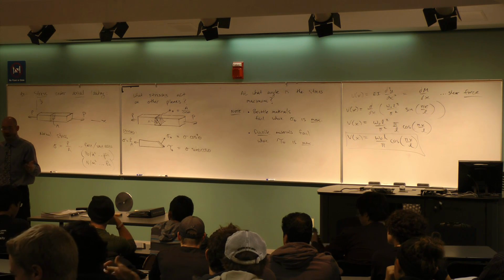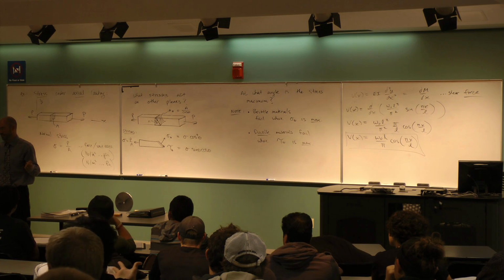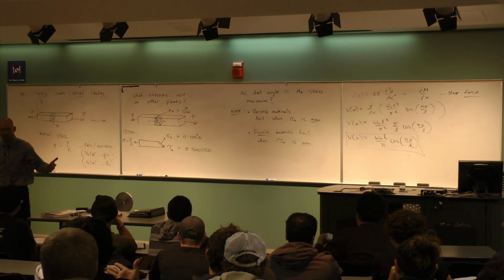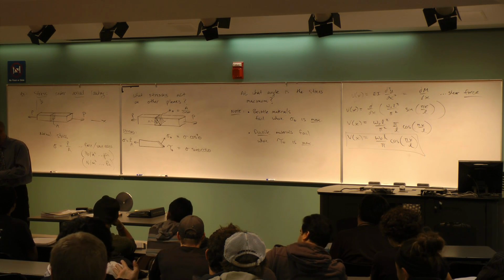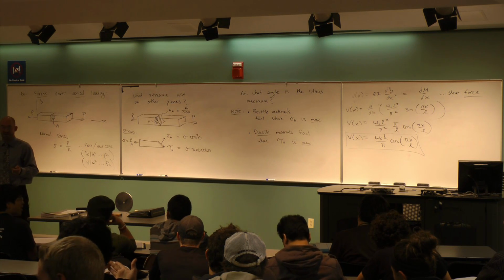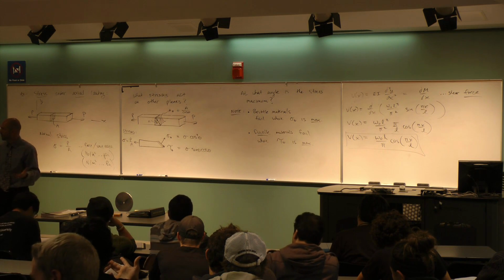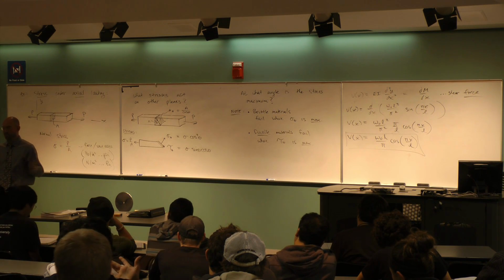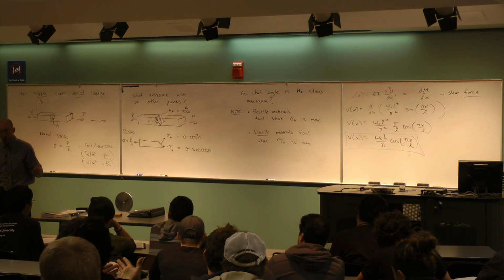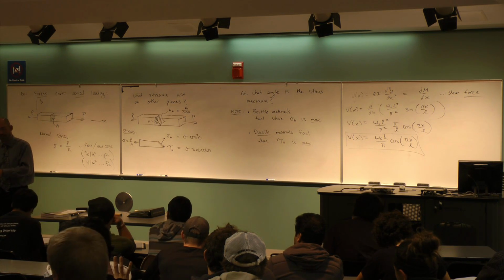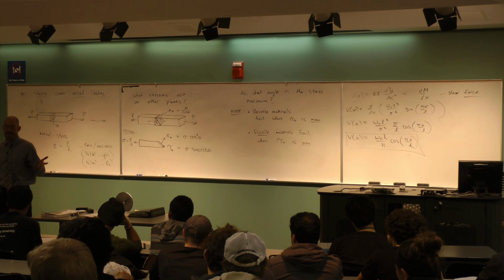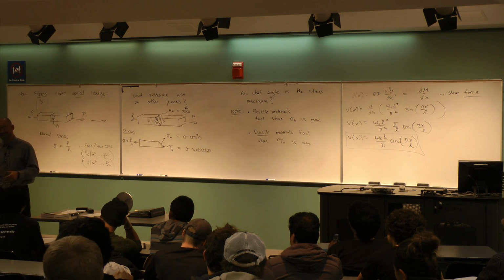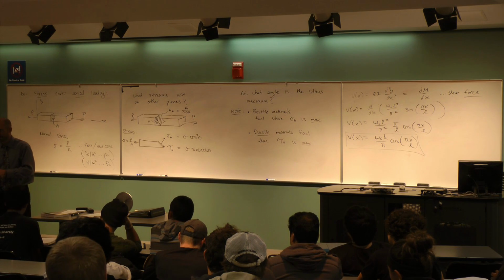Steel. Aluminum. Copper wire. Copper. Nickel. Tungsten. Titanium. Zinc. Metals in general, unless they're processed in a way that makes them brittle, like casting, all right? Cast iron ends up brittle. So it depends on the processing, but steel, everything's steel, pretty much ductile. Although, if I make the hull of my ship steel and I sail it in the Arctic Ocean, it depends on temperature. If I heat things up, they tend to be more ductile. If I make things really, really cold, they tend to be more brittle.